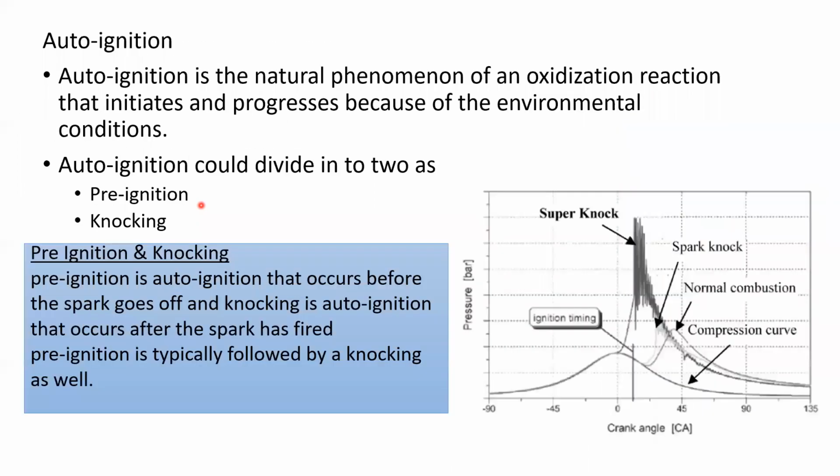Knocking is actually something called auto ignition. Auto ignition is the natural phenomenon of an oxidation reaction that initiates because of the environmental conditions inside the combustion chamber.